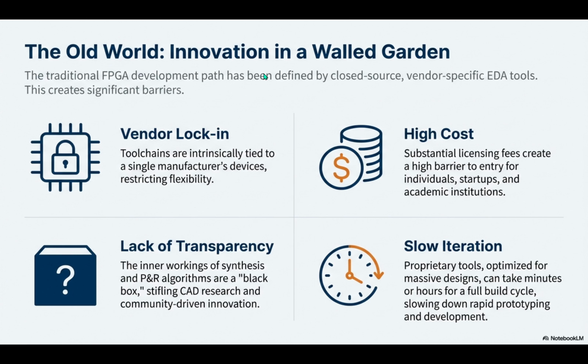Well, historically, engineers were dealing with what the sources break down into four major roadblocks. The first and maybe the most obvious one was vendor lock-in. The tool chain, the entire suite of software you need to turn your design into a working chip, was completely tied to one manufacturer's specific device family. So if you invested all this time and money training your team on, say, the Xilinx suite, and then you wanted to move to a Lattice chip, you had to scrap everything and start over. Exactly, you'd scrap that institutional knowledge and begin from square one with a totally new software environment. That lack of portability was a massive restriction on your technical freedom.